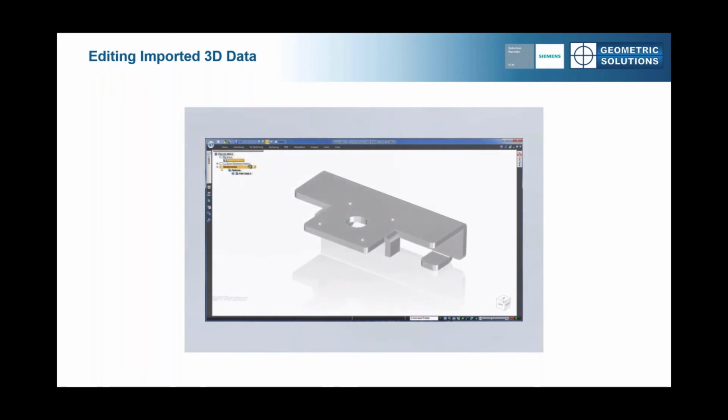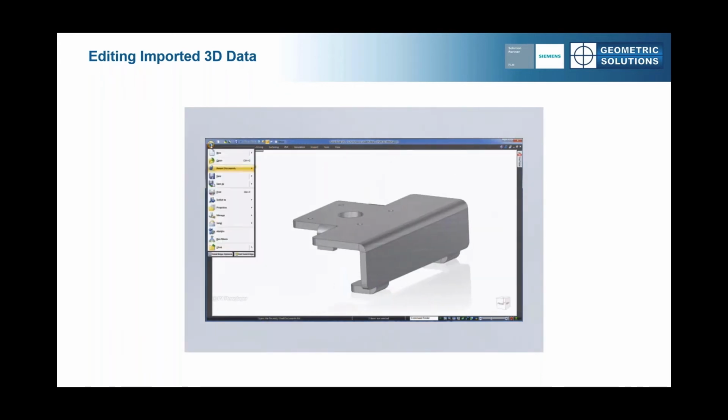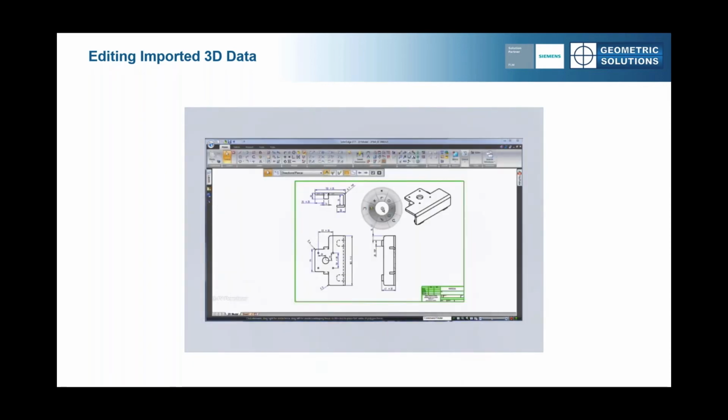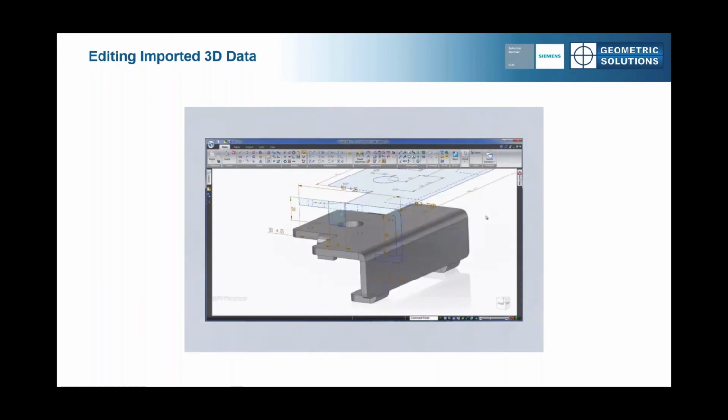Now, not only did we receive the 3D sheet metal file, but also its manufacturing drawing in .dwg format. Wouldn't it be great if we could make use of this drawing to assist us with any edits and also provide tolerance information, all in 3D? Well, check this out. Once we open the DWG inside Solid Edge, we can use a simple tool to grab the information we want just by fence selecting on screen, and then apply that information to our 3D model.